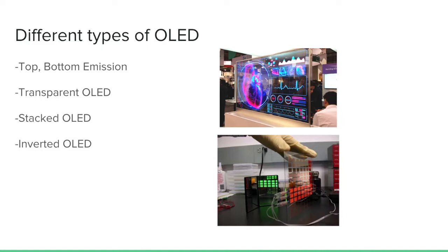The second type of OLED we're going to go into is top emission. Top emission OLED devices are devices where the light emitted exits through a lid that is added after creating the device. These top emission OLED devices are better for AMOLED due to the non-transparent substrate used under most AMOLED panels.